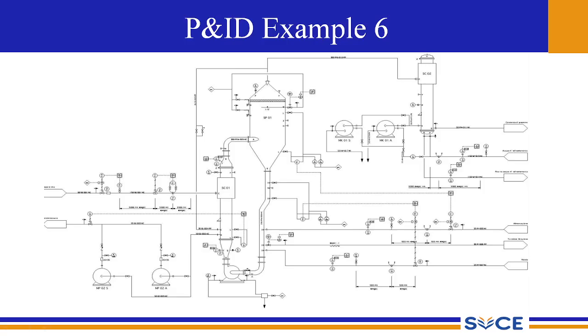Next is an example of a P&ID diagram corresponding to an evaporative crystallizer. So this SC1 will stand for the crystallizer, and the SP1 stands for the evaporating arrangement with a downcomer. The legends of the pumps and the corresponding valves and the connector diagram symbols are actually shown in this picture. You can have this flow sheet as a practice to understand the process flow of an evaporative crystallizer.